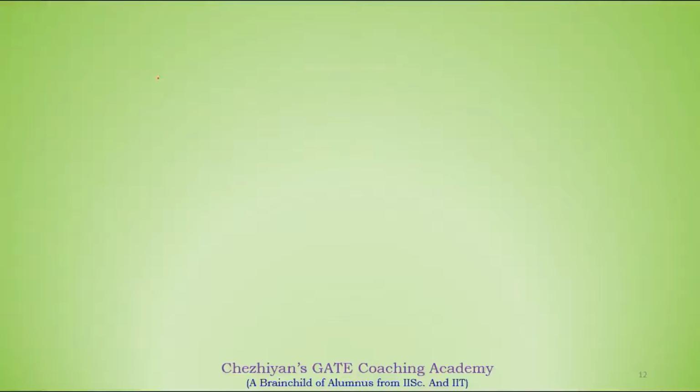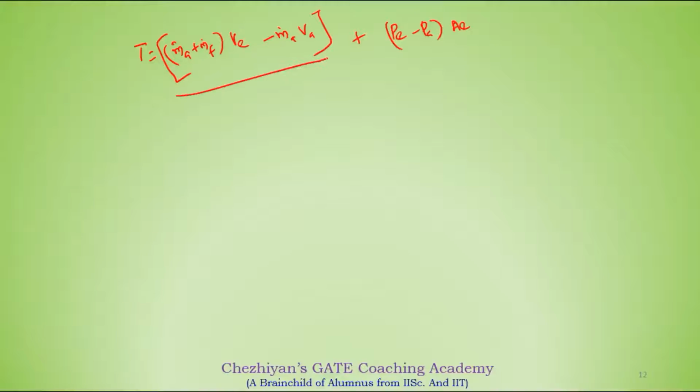So we know the thrust equation. That is going to be (m dot a plus m dot f) into VE minus m dot a into VA. What we call this one is the momentum thrust. Next one is (PE minus PA) into AE. What we call this one is your pressure thrust.